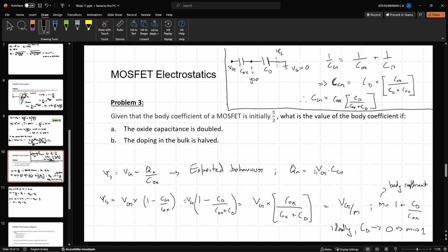So the static charges in my system will not be present at all. Therefore, any charge that comes into my device directly forms the inversion layer, and my device is ready to function. So I will just have a small minor threshold voltage that I will have to clear, and the threshold voltage of course can be determined directly from the doping concentration. That will tell me where the quasi-Fermi level is. I know the band gap of the material. So from the difference of the two, I can directly determine what gate voltage I need to apply to achieve inversion.